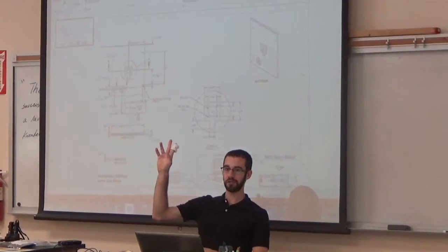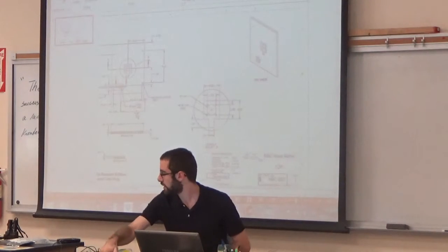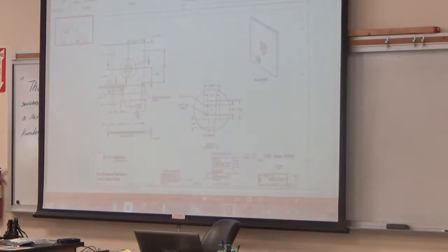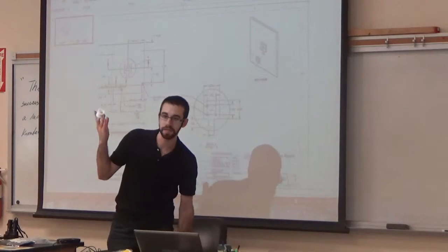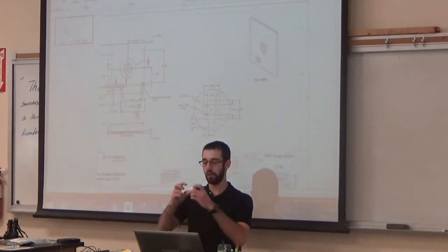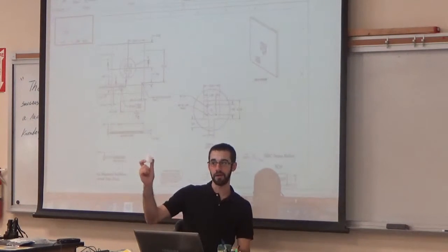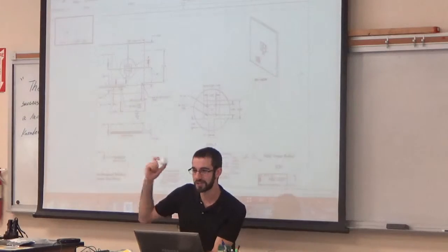I used to work at a faucet company, and if you have a sink right here, this piece goes right here. Your faucet coming out right here goes onto this. And there are two O-rings that go around here. O-rings are rubber gaskets to stop the water leaking. Well, you can't tell by looking at this, but one of these circles' diameter is smaller than the other. And what did that cause? Anyone can think? Leaks, yeah. So this caused leaks.